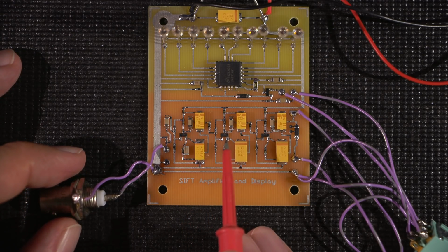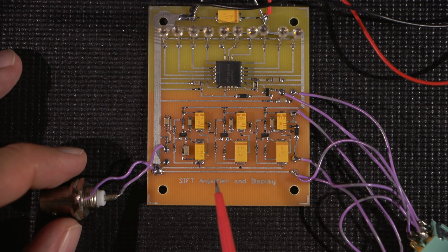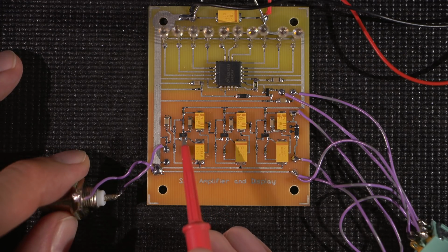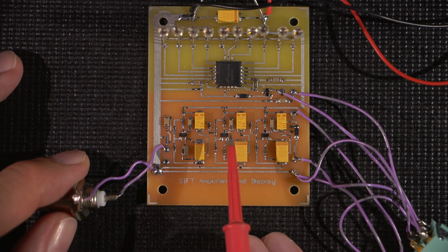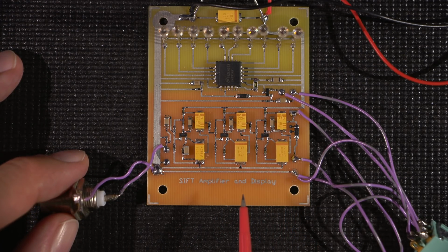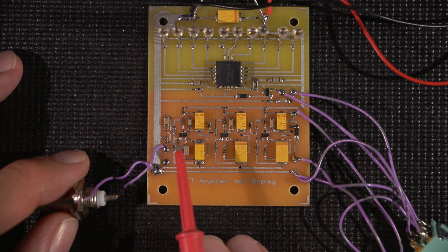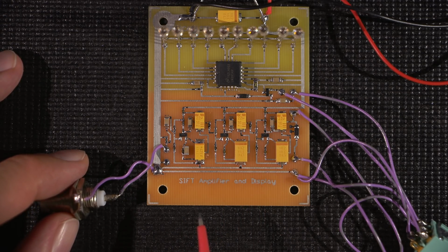And then as you move along, you're going to be adjusting the scale on your oscilloscope. Basically, you're going to be adjusting the vertical sensitivity as you go along, because the signal is going to start to get really big when we get over to this portion of the amplifier, right? Because it's getting amplified up to a very large state here.